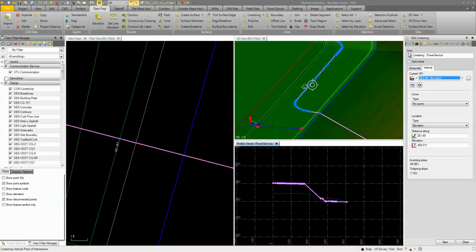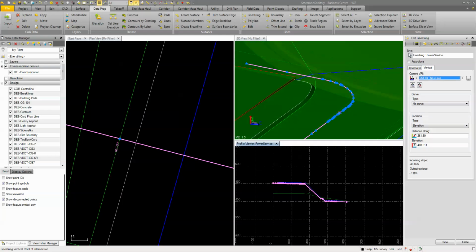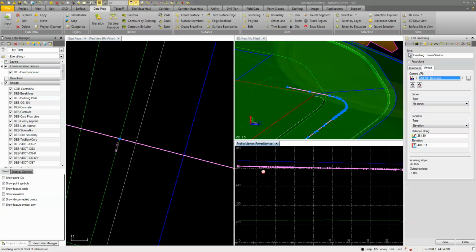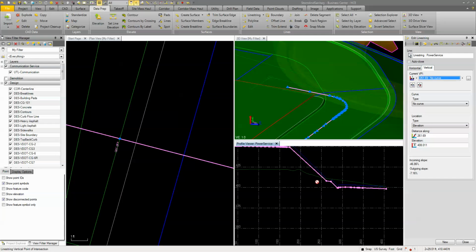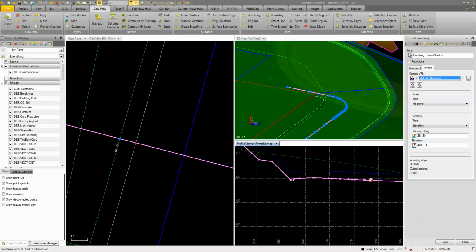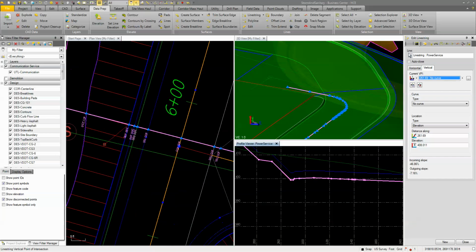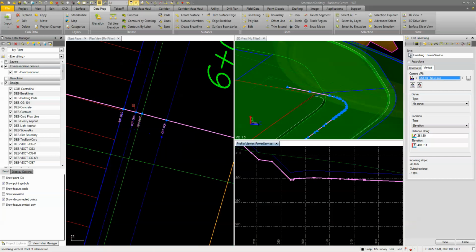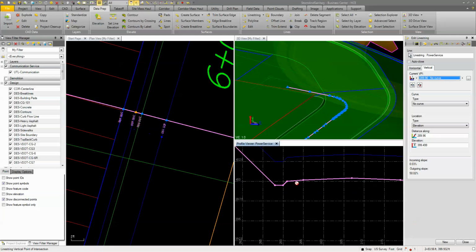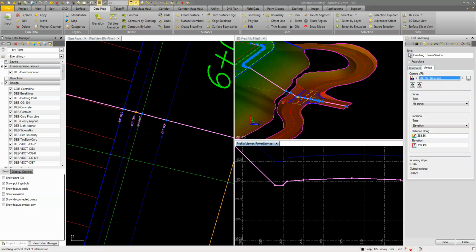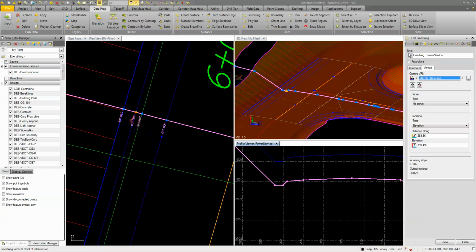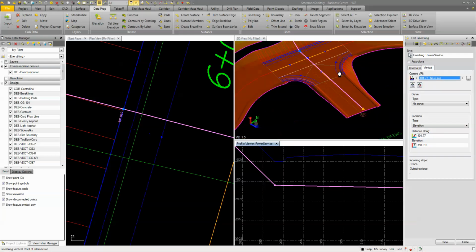The rest of these I guess we can leave. I'm just kind of trying to smooth it out a little bit, make sure there's no big jumps in here. I mean, that's fine. Down here we're good. We want to drop across the road. We're just going to go straight across. So our low spot is this one, and I'll look over here. So there's our low spot there. That one actually is. So we'll delete this one. I'm just going to delete all these, and leave that last one there.